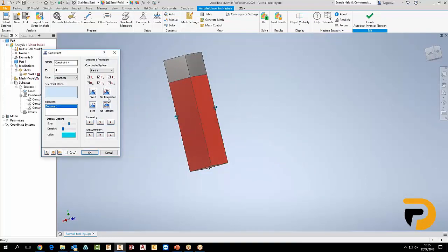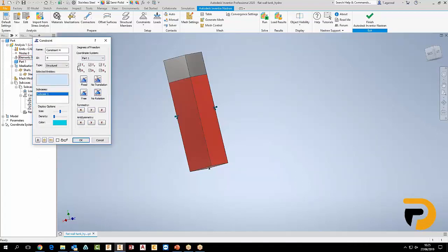So just to explain what those are, there's basically degrees of freedom. So people that have been using Inventor will understand what I mean by degrees of freedom. A part's got the flexibility in all axis or movement in all axis. So what we're doing is we're able to constrain on a particular axis and apply that constraint as well. So definitely. Yeah. That's a good point to note. Like, these are all the 6 degrees of freedom. So translation TX, TY, TZ, and rotational RX, RY, and RZ. Okay, so we can choose these according to our need.